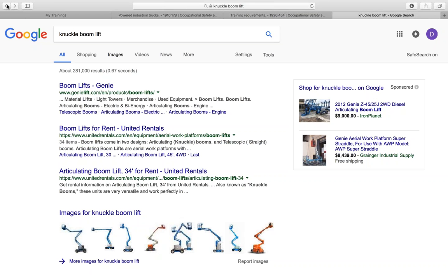Okay. Also, we have to make sure that all guardrails are in place and locked into position. We have to perform the operator's checklist, the checklist that comes with the manual, and check all the components and fluid levels, including fuel, oil, hydraulic fluid, and coolant levels, all of the liquids and fuels that we need to check on that vehicle to make sure it's performing safely and optimally. And then we never make unauthorized modifications to that aerial lift. Okay, so those are all requirements that we have.